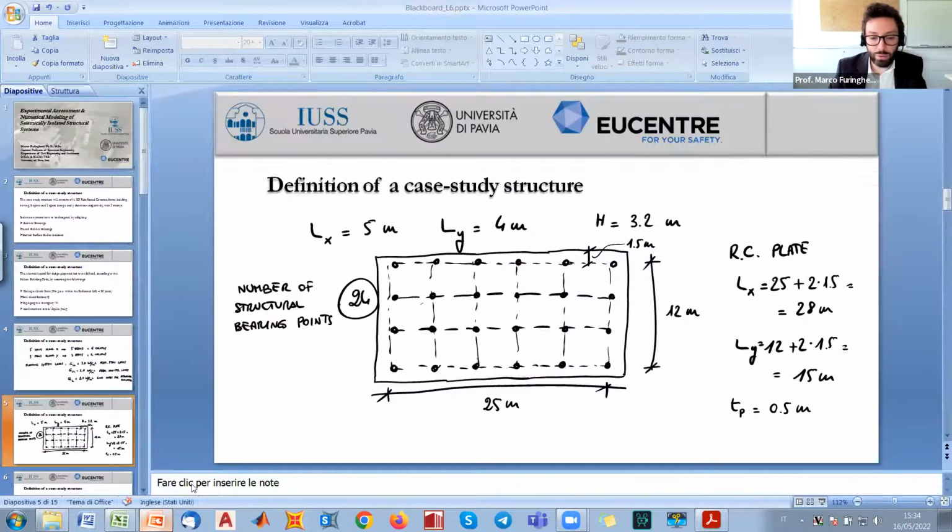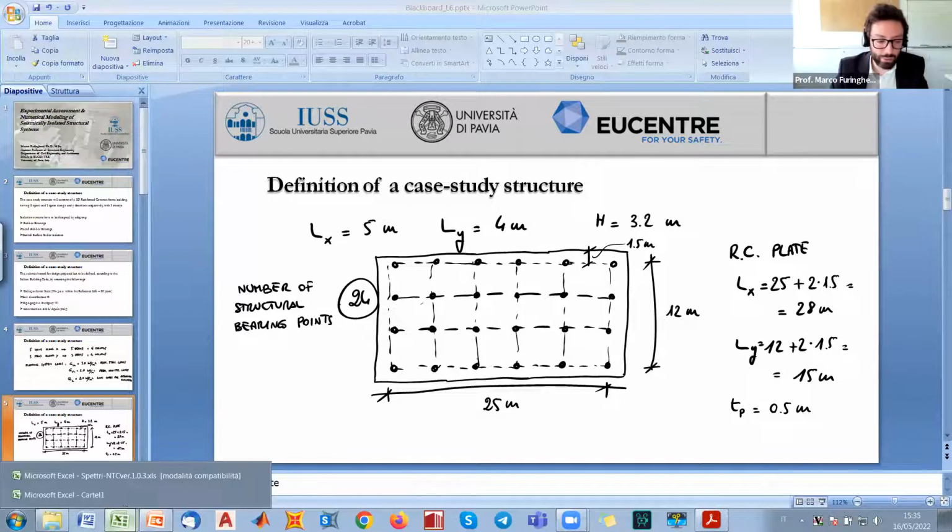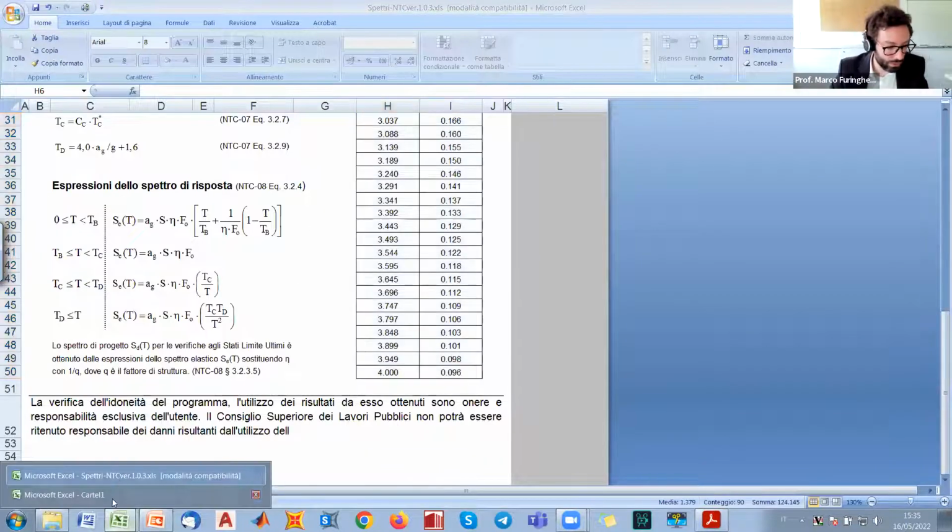But if you go back to your plan view, how do you place 10 isolators in a symmetric way? It is actually impossible, simply because you have an even number of beams along the x, and the same along the y. So the best is to get an even number, and also the halved number should be even.